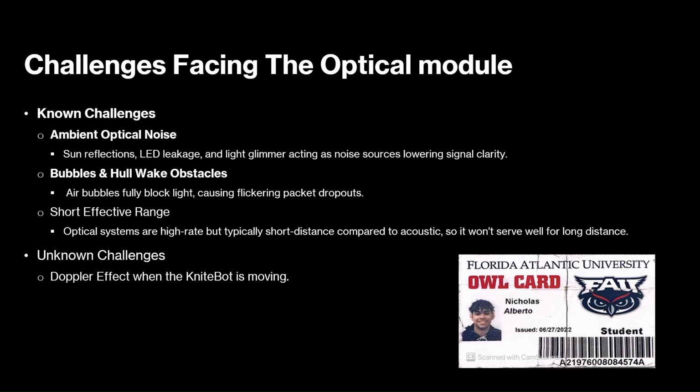Challenges facing the optical module. Known challenges are ambient optical noise, that being sun reflections, LED leakage, and light glimmer acting as noise sources, lowering signal clarity, bubbles and hull wake obstacles. Air bubbles fully block light, causing flickering packet dropouts.